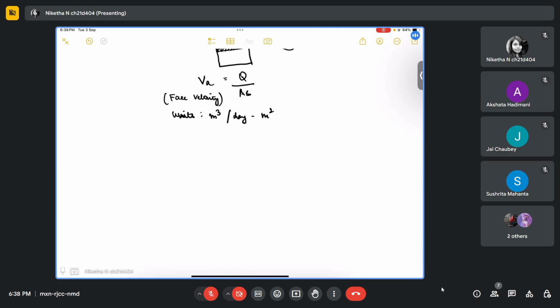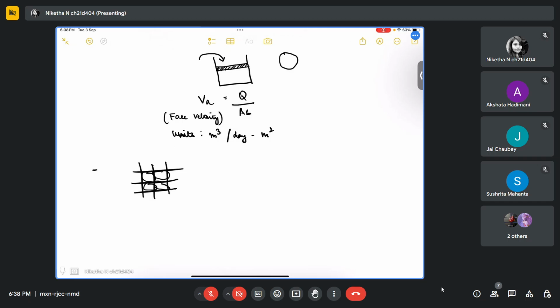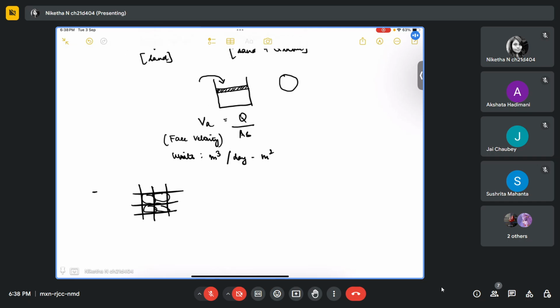Sometimes when we have water that is highly turbid, imagine you have a filter like this with this pore. If you have water with high turbidity, then the filter pores could get clogged by the colloidal particles. So in order to remove them, we will do a procedure called backwashing. After filtration, generally the pores will be slightly clogged.